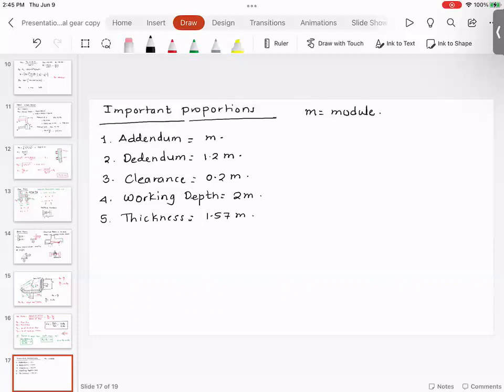And so here is the general process. In the case of helical gear, when we tried to design, we found out the equivalent number of teeth on the helical gear. So basically the process for the helical gear design is exactly the same as the spur gear design. Only thing is we took that helical gear and converted it into an equivalent spur gear. If you think about the helical gear, it's in the same plane as the spur gear. But the bevel gear is actually a three-dimensional structure. So it's actually a 3D gear.